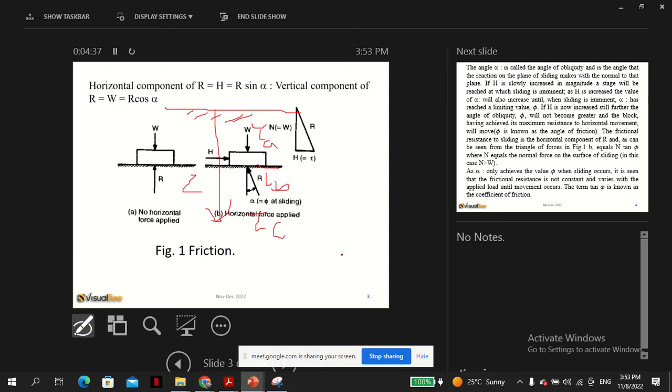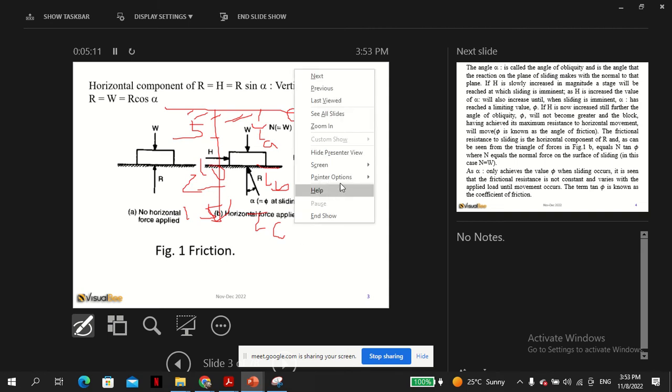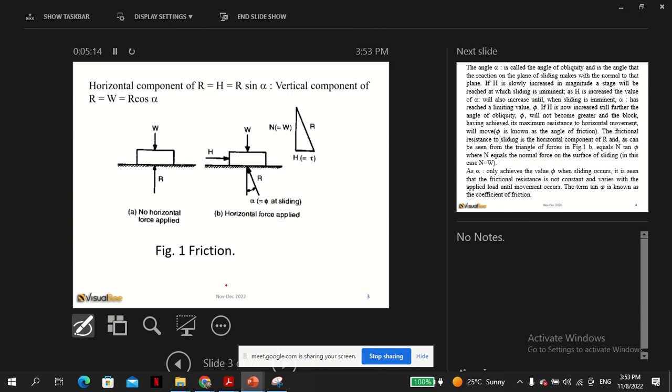I think it's tau C. Exactly, because the confinement is increasing. The sigma n here is gamma times a small z. Let's say here is 5, here is 10, and here is 15. Because z is increasing, the confinement is increasing, so the taus must also increase. That's the first thing we need to learn.